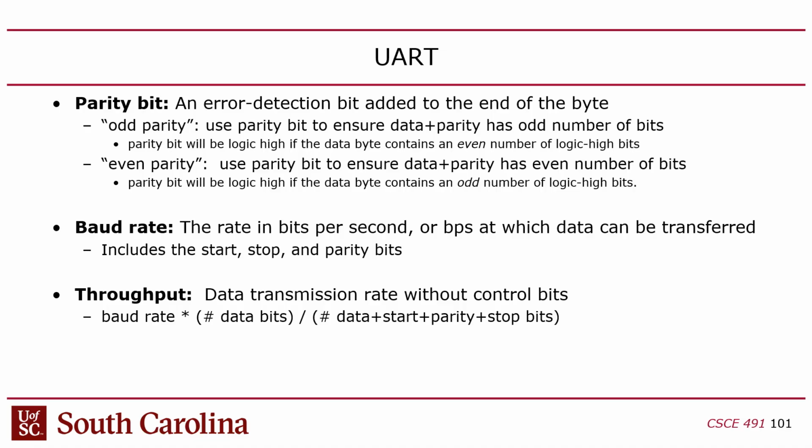I think that makes it a little easier to interface, because I think UART is more common as a protocol than SPI, especially if you have a really low cost chip. But I don't know the whole history of it. In my experience, I usually use it as a terminal. Also, Arduinos are programmed over UART. You actually send the program code through UART, and I think the reason for that is because when you have a USB connection to a single board computer,